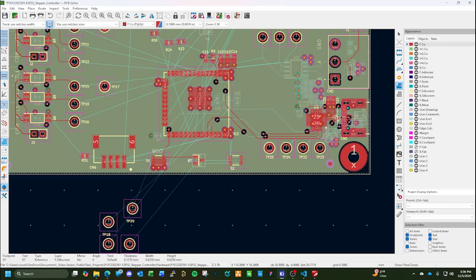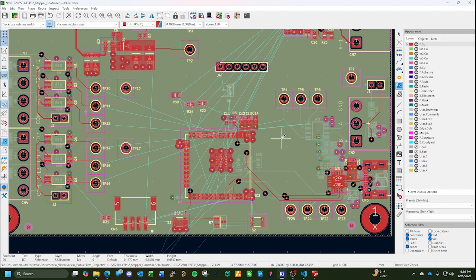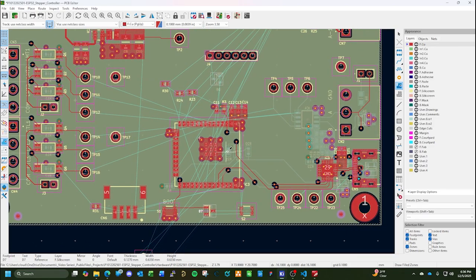USB connector, I've got a couple of TVS diodes over here protecting some of the input circuitry. The RS485, since a human can touch these inputs, I've got a TVS, so it's just a common practice. And then the FTDI cable interface, I've got another TVS diode, because humans, again, will be touching that and they can send in a shock, which can damage components.